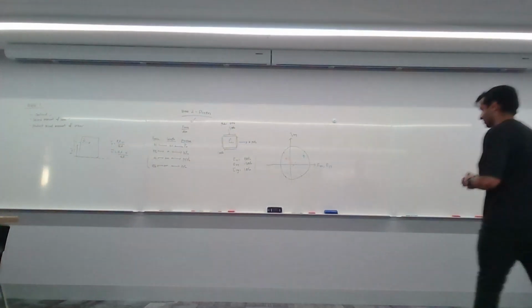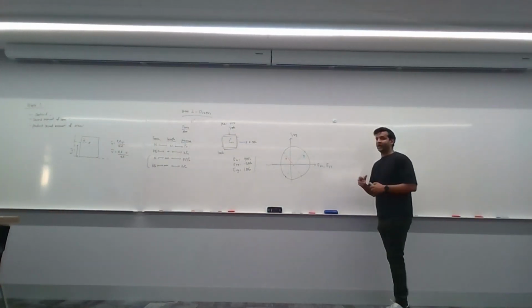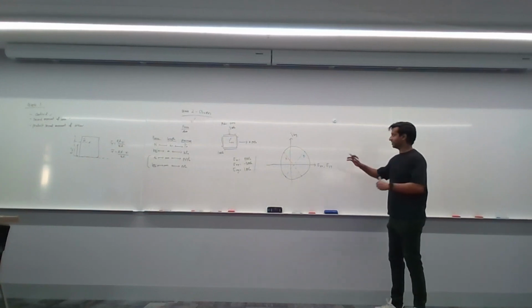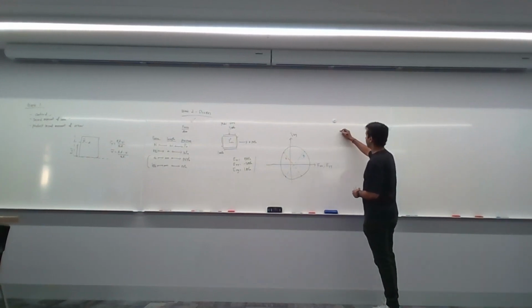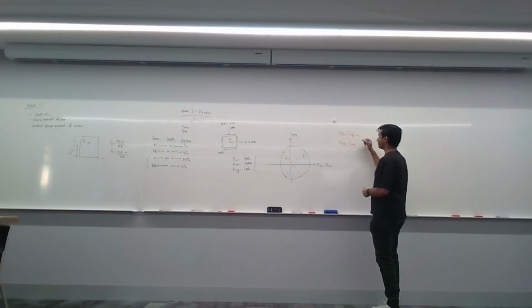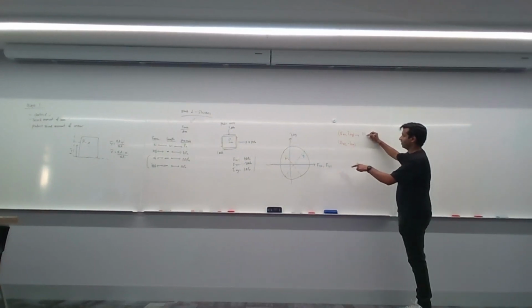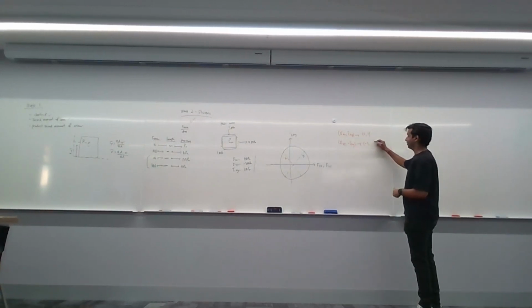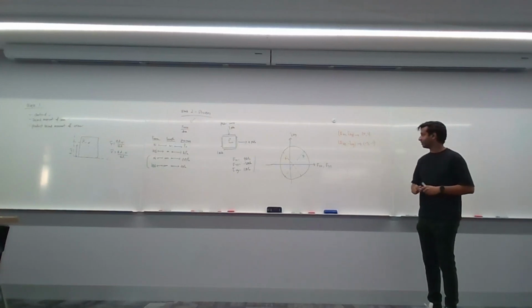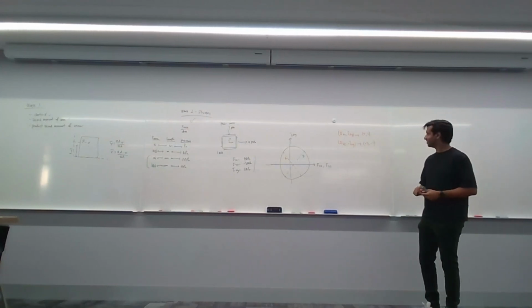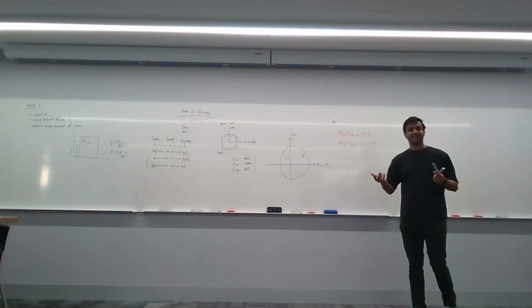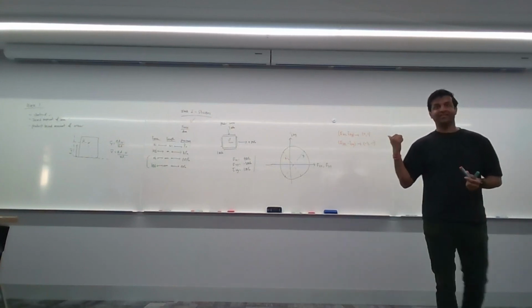Okay. Let's ask ourselves first, what are the coordinates that I have to plot? Remember, it's the same thing as the I value Mohr circle. The coordinates that I plot are sigma xx and tau xy, sigma yy and negative tau xy. Okay? So sigma xx here is 4 and tau xy is 1. Sigma yy is negative 3 and the negative of tau xy is negative 1. Okay? So, A or B?